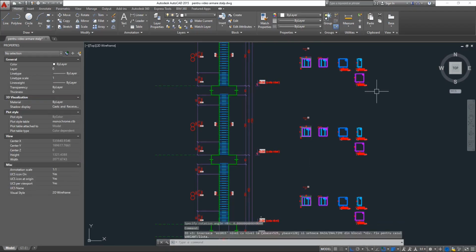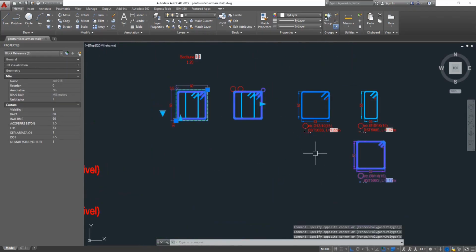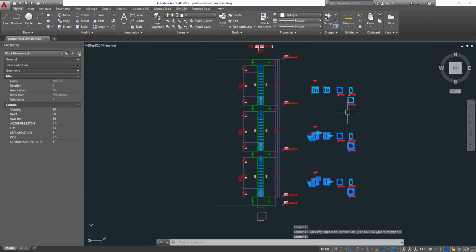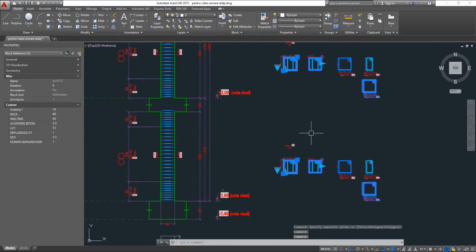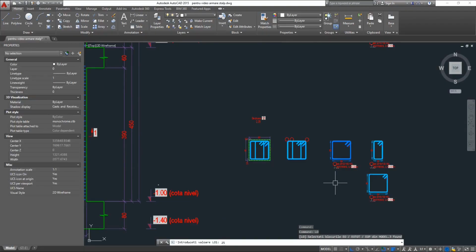Now we're going to put on the same elevation another set of stirrups, horizontal ones this time. They're building themselves on the elevation. We're going to choose for them as well a 10 millimeter diameter. And again, we want them on each level to be over 25 centimeters width.